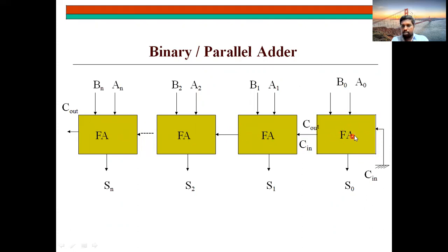And then when these are operated, directly you are getting values at your output, and each and every C out becomes C in for the next one. Okay, so this is called your parallel adder. Parallelly the addition will be done, and parallelly you will get outputs S0, S1, S2. So just learn this circuit diagram. Full adders will be in a sequence.